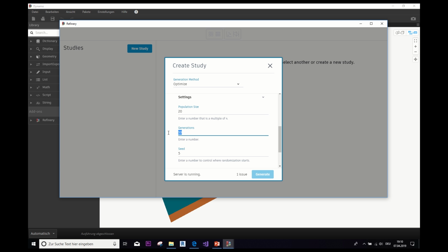So basically you need to switch it up a bit to see what results you get after 10 generations. Do I get better results if I enhance it to 15 or 20 generations? And then you will see, so start low and then increase the number of generations if you're not satisfied with the results. And then population size is how many designs will be generated per generation.